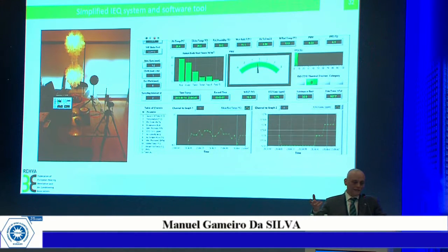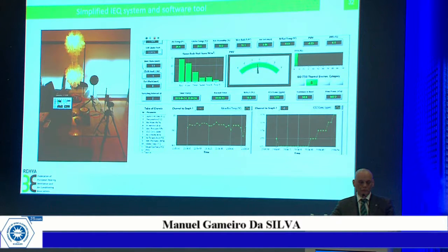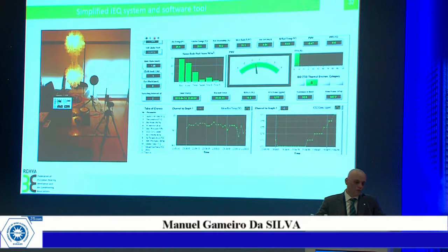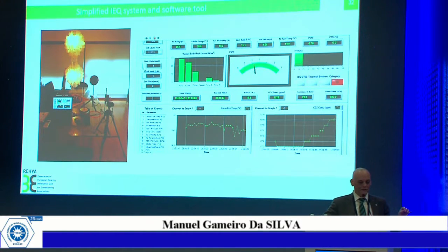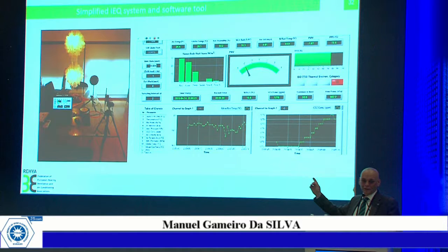so I started with, let us say, normal winter conditions. For a sedentary person, with a 1.2 metabolic rate, and I think 1.0 clothing. And I first decreased the metabolic rate. Imagine that you are in your room, and it happens very much, you start sleeping. And typically when you wake up, you feel cold, you feel uncomfortable. So that's what happened here.